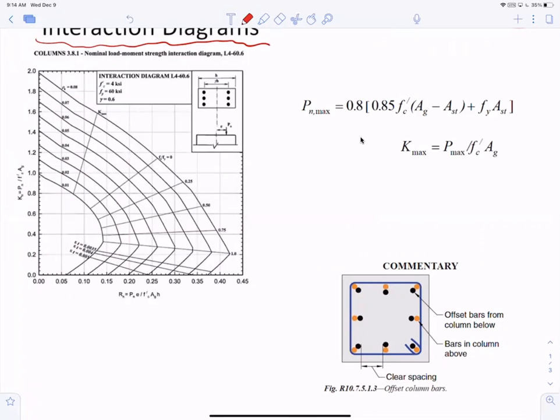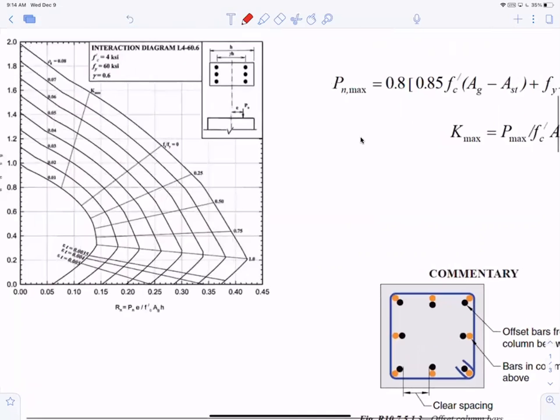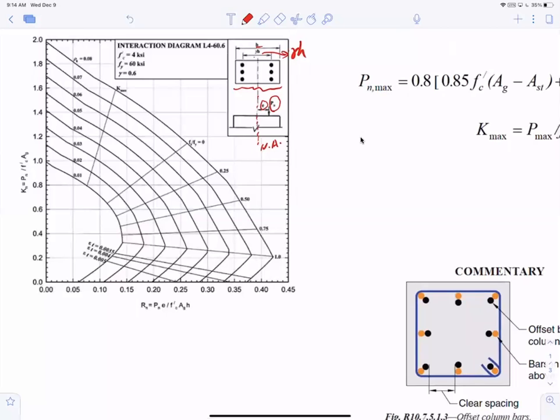From the definition of a section, you can see I have the height, h, at the top right here, and I have a distance between bars as gamma h. That means I can tell you the position of the bars from here. If I apply the axial load Pn with an eccentricity e with respect to the neutral axis right here, then this chart is calculated based on this configuration. You can plug the numbers in to get the section, but right now we can assume we don't know the section. This is just some relative ratios, and this is what we're seeing here.